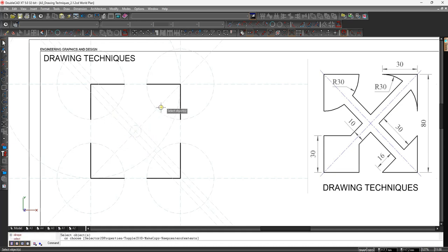And to draw the parallel lines to this waterline, which is my middle line in this case, I'm going to select one of those lines. So I have to select my perpendicular tool again, and I'm going to click on one of them, and now I'm going to snap to that 5mm distance. Again, use the perpendicular tool and snap to that edge of that circle. Now I know that from one end to the other we have a 10mm distance on these bars that go diagonally.